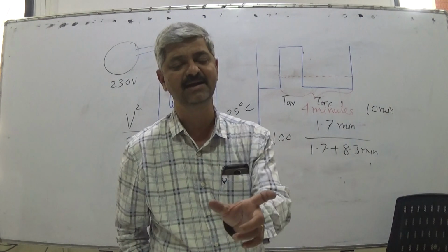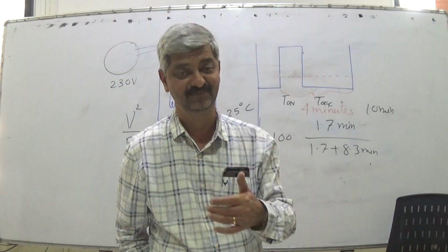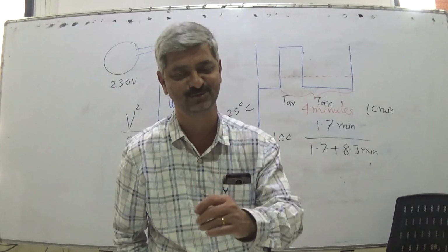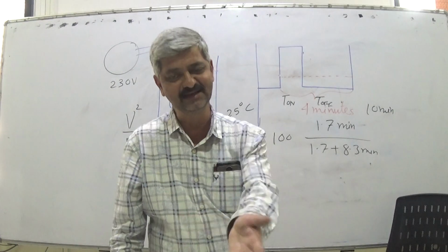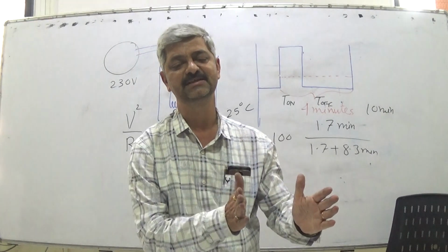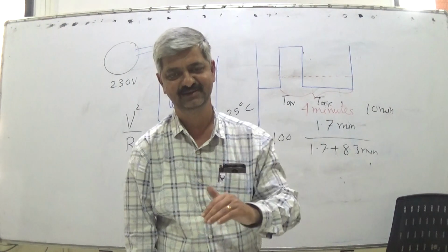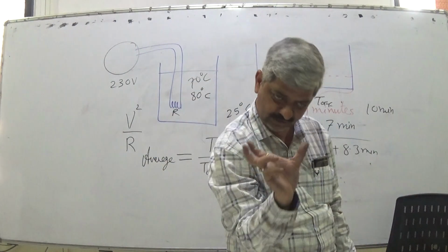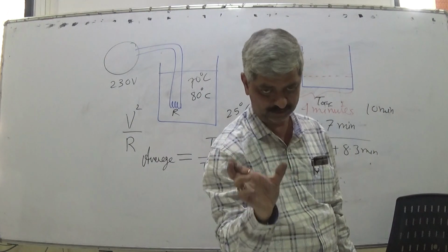The best way is a 100-second cycle. 1 second on is not good, because switching on and off that fast is also a problem. You can have 1000 seconds or 500 seconds, say 10 seconds on, 490 seconds off, which gives 2%. So effectively, over the total window you give the average output for the total duration.